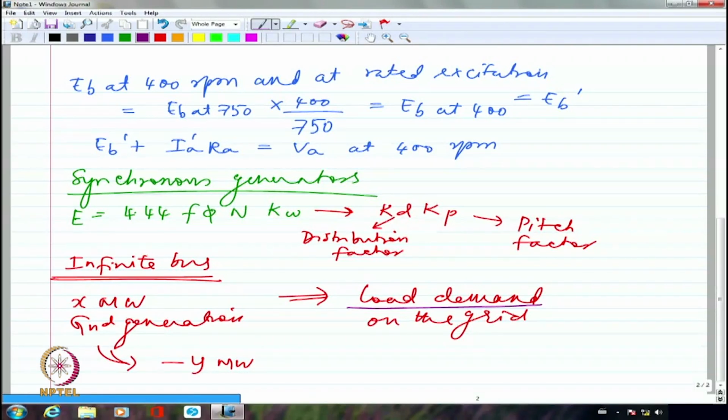So what is going to happen is, if people have not noticed and have not switched off many of the loads in Delhi, which is a power guzzler normally, then eventually it turns out to be an unstable condition, because the frequency will fall, because the speed will fall, and eventually it will become extremely unstable. The entire thing conks out.